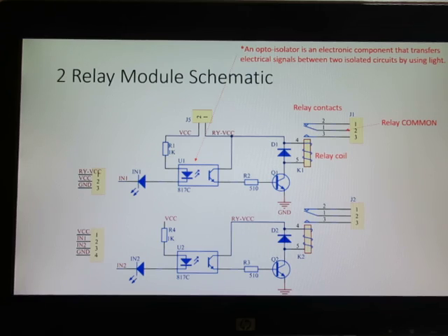So when we ground the diode at either N1 or N2, right here, the optocouplers U1 and U2 will light, and the lighting of the optocoupler will turn on the phototransistor. So here's U1 and U2. There's the phototransistor. This is internal inside that integrated circuit. So the phototransistor, once it's activated, will send VCC to the base of the NPN transistor. So it'll turn on Q1.